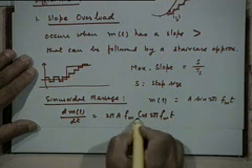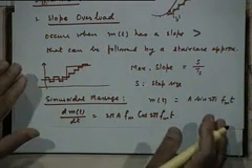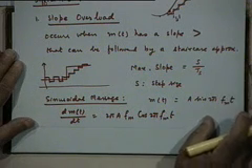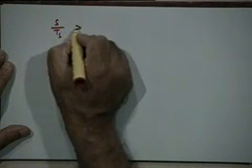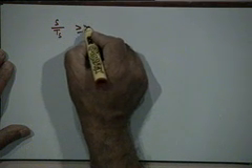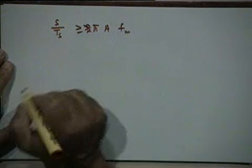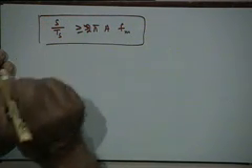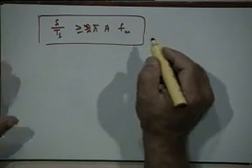Two pi A F_M, right? So what is the required condition that for this sinusoid we never face the slope overload condition? We must have S by T_S greater than or equal to 2 pi A F_M. So if you want to avoid slope overload, you should satisfy this condition for a sinusoidal message.